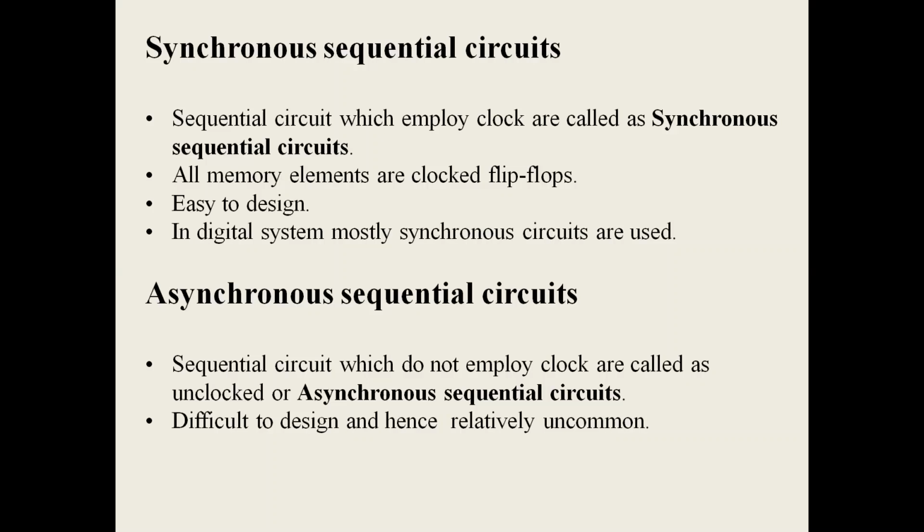Whereas sequential circuits that do not employ a clock are called unclocked or asynchronous sequential circuits. They are difficult to design and hence relatively uncommon. One thing more I want to say here: in an asynchronous sequential circuit, the output of one flip-flop is basically the condition for triggering of the succeeding flip-flop.